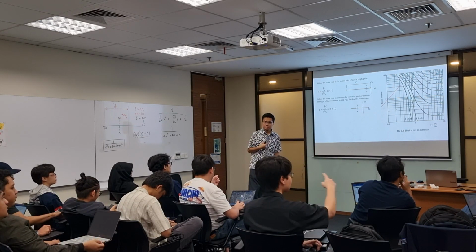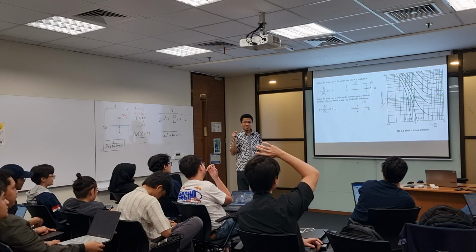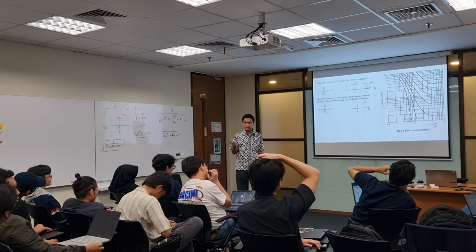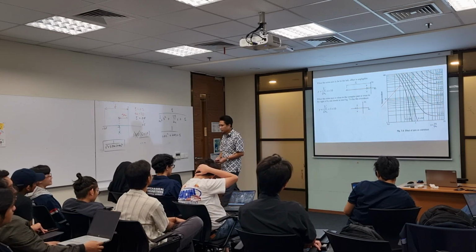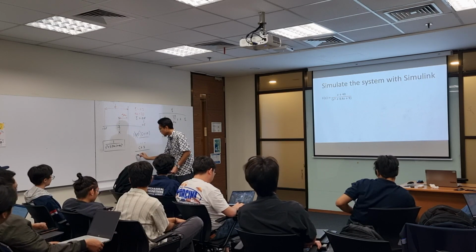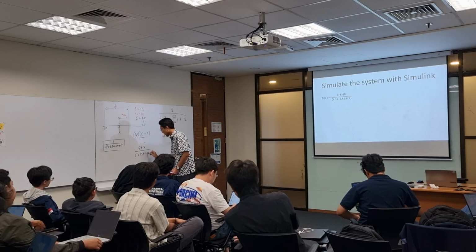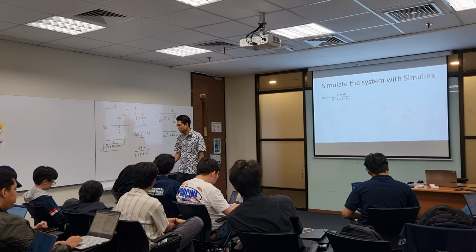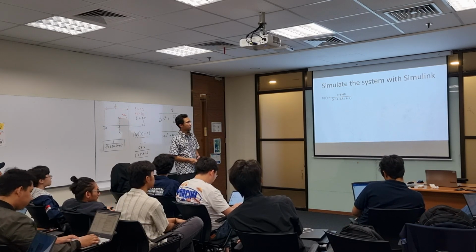Any more questions on this? For a second order system, that's correct, a second order system which has an extra zero. For example, if you have s plus 3 on top and s squared plus 2s plus, let's say, 1.5 below, then this applies. It is a second order system, but you have a zero on the top.